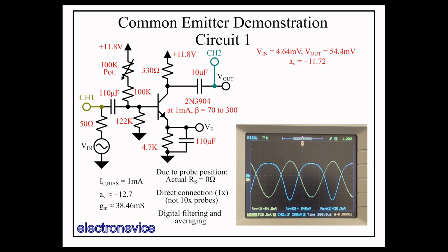And as we keep going, we can finally see the top of the waveform flattening. This is because we've pushed the output signal high enough that the collector current is shutting off, because the input signal voltage is going so low that it's actually causing the transistor to turn off, and the output cannot go higher than its positive rail. And we see that increasing the input signal further causes the low portion of the output to go lower, but the tops of the waveform don't go any higher. You'll note that the maximum voltage output isn't very high with this particular circuit without getting very nonlinear.